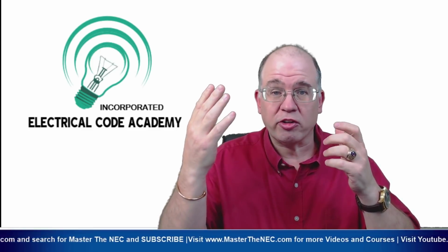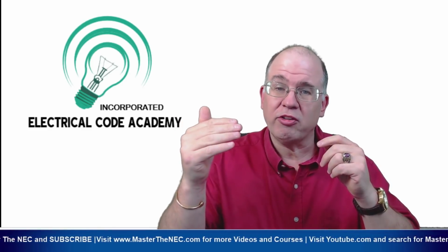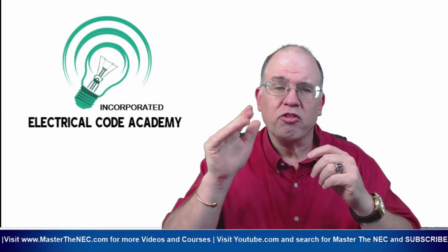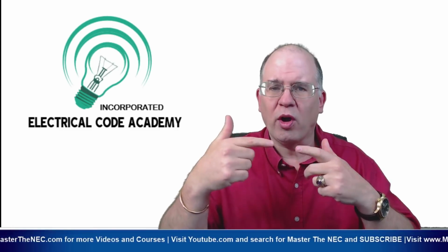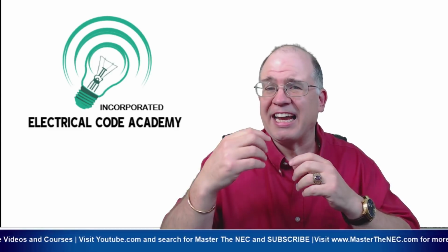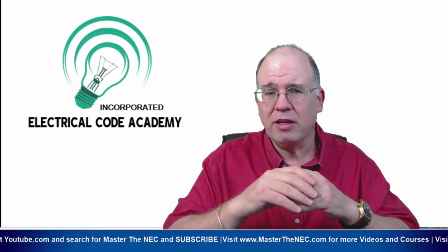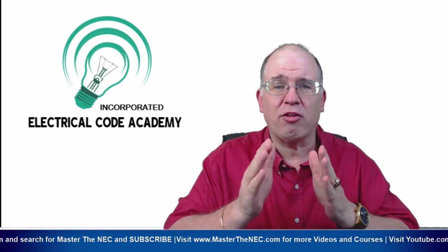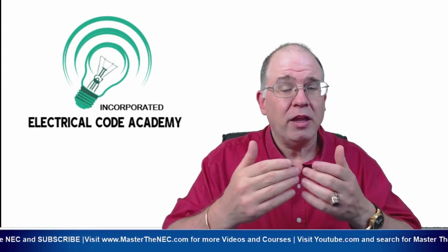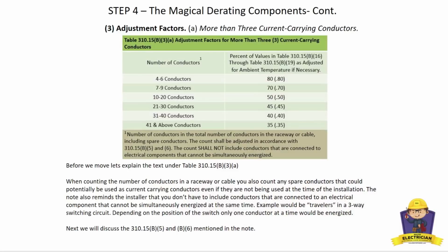So the circuit conductors come in. The hot conductor or the ungrounded goes to the common terminal, supplying power to the switch. And then you've got a little switch in there that switches back and forth to the actual traveler terminals. So at any given time, current is traveling on one of those travelers, but it's not traveling on both of them at the same time. So if I was doing that, I get to discount one of them and only take one of the conductors as a current carrying conductor for this application, because it's impossible for current to travel on both of those conductors at any given time. So where you have equipment that utilizes this application, then you're able to use this rule here for that. Okay? And that's what the note actually is referring to there.